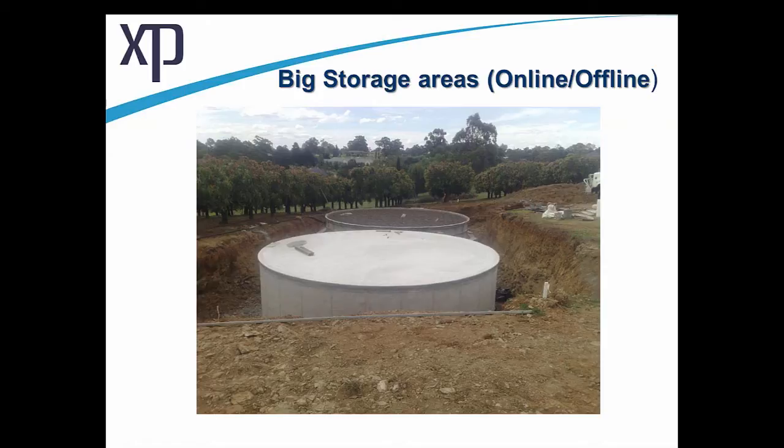Another way to mitigate the flooding is raising the thresholds of important buildings, such as subway stations. So we don't want to have flooding in the subway station as soon as the flooding hits the area. This is very important to protect the buildings and reduce the impact of flooding in some important buildings. So the use of raised thresholds makes a really big difference in managing flood and building resilience in our buildings.